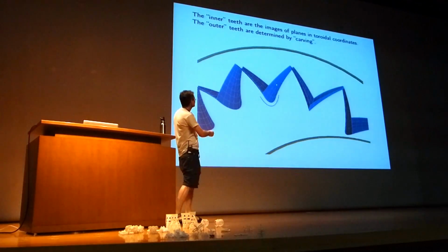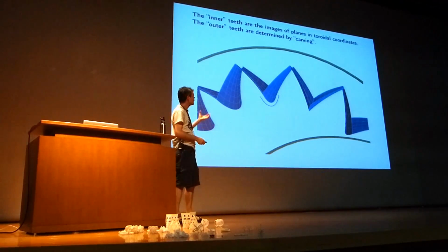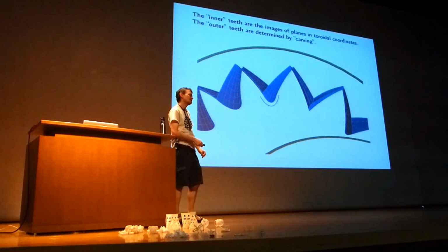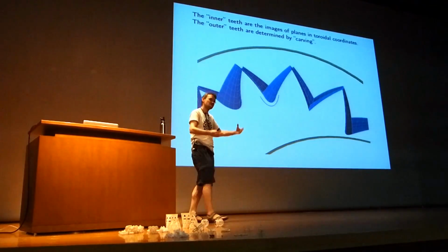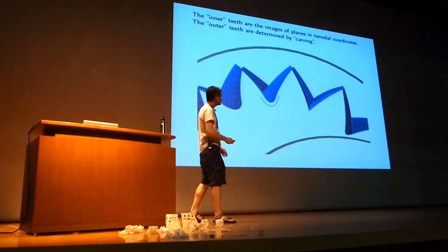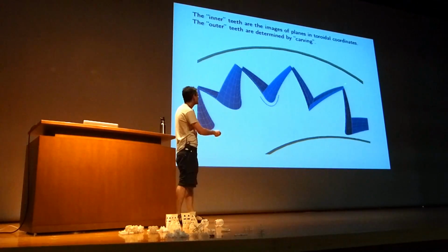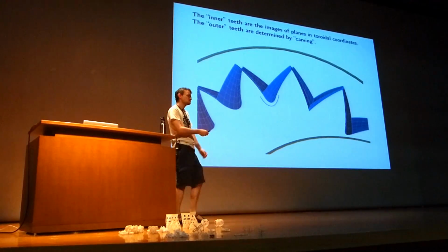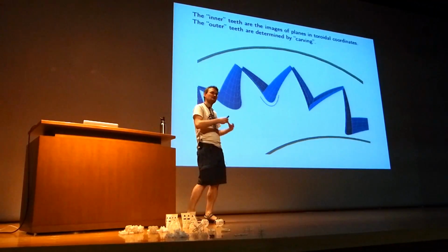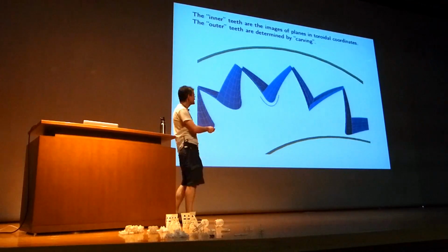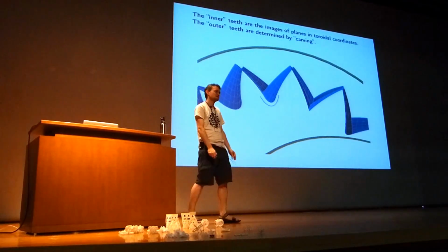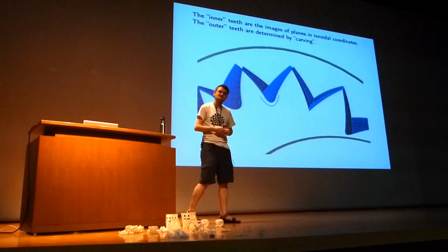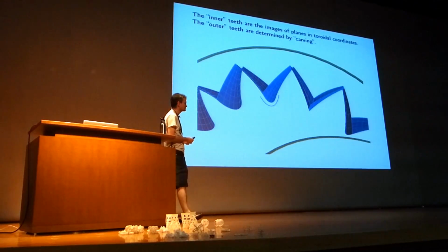So what do we do instead? We've decided on these gear teeth, and the idea is this. We know how these 2 rings are supposed to rotate relative to each other. Let's imagine that we've made these gear teeth on this ring, but that this other ring is made out of clay. Then we move both of them forwards and see what shape these teeth carve out of the other ring down here, and use that shape as the gear teeth on the other piece.